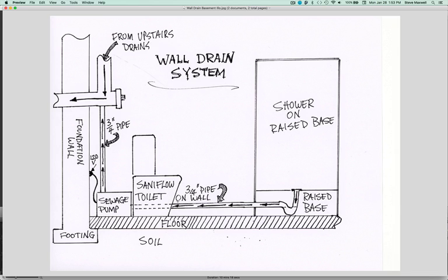You're also going to need to do some fooling around here to see how high you have to raise the base so that you have room to get the pipe in and for it to go horizontally. You're going to want to make this raised area accessible too, because who knows, someone might need to get in there someday. So as much as possible, you're going to want to leave it accessible. And that's really the only way that you can get any kind of sewage to drain away in a basement where the outlet is partway up the wall like this.